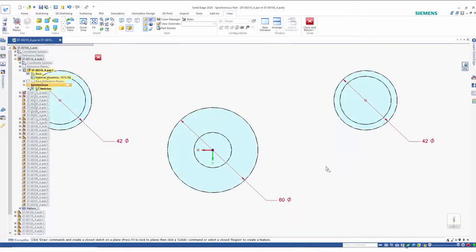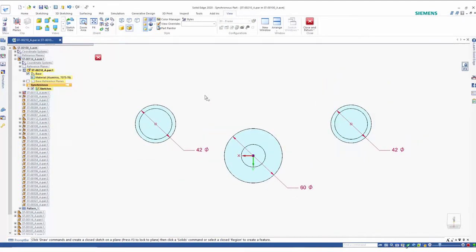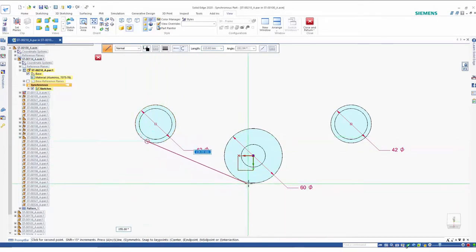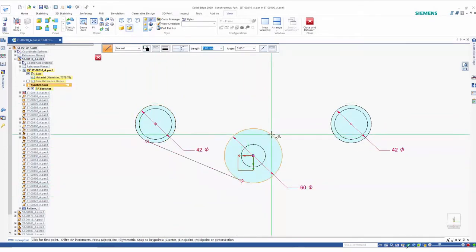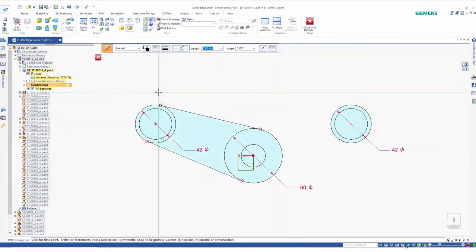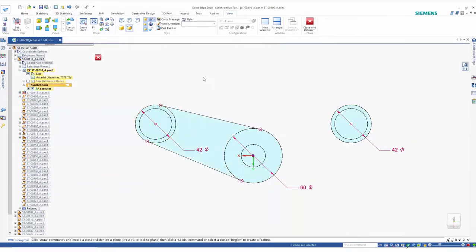Solid Edge supports a full complement of drawing commands. The heads-up display also makes it easy for us to see where we are relative to other geometry upon creation, as well as other critical feedback. In this example, we can quickly complete the main shape of the part by using a common sketching tool to mirror geometry and finish up with a few 2D dimensions.